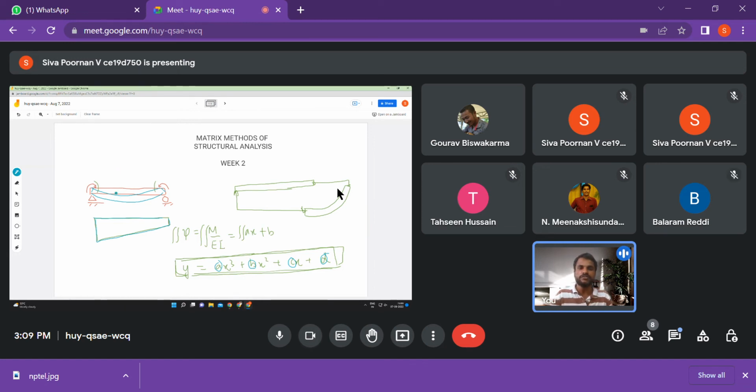We'll convert it into an end load. If you remember, even in your basic analysis, you would find something called fixed end moment and then convert it into moments and then do the analysis. Okay. So I hope this has given a better perspective of why we are using only rotations. That is true only because we have nodal moments or nodal loads, not intermediate loads.